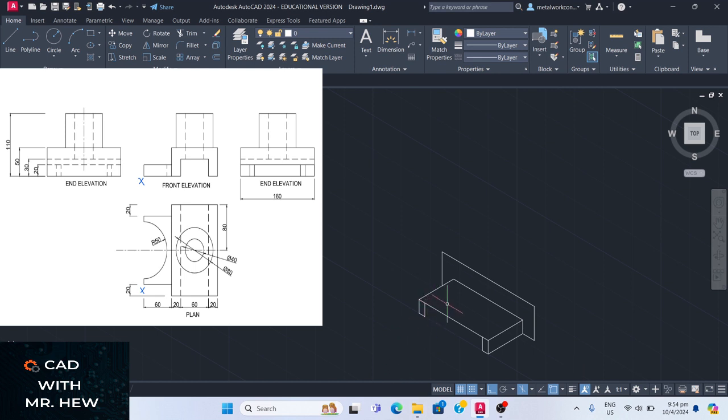We're going to complete drawing the box here, and then we come back to draw the semicircle. So we have gone up 50. We have to change back to the right isoplane this way. The length here would be 20. Line, going up 20, and the height would be 30.